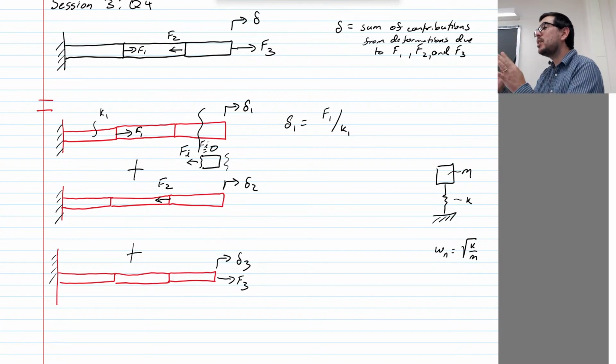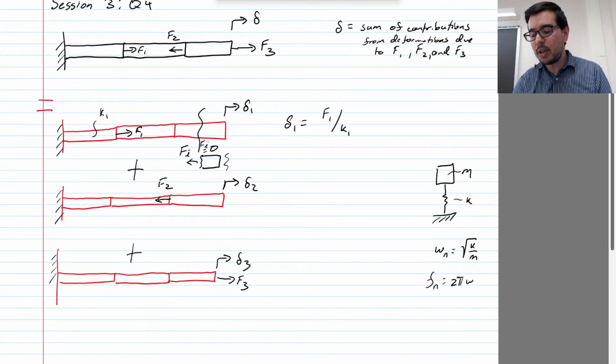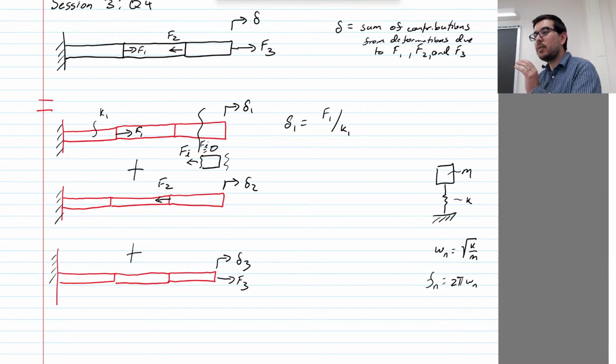But what happens is there is a resonance of your washing machine, and it's frequency dependent. Okay, so omega n is in radians per second, so the frequency is equal to omega n over 2 pi. As that thing starts spinning, it's really wishy-washy in there because you actually go through the resonance.